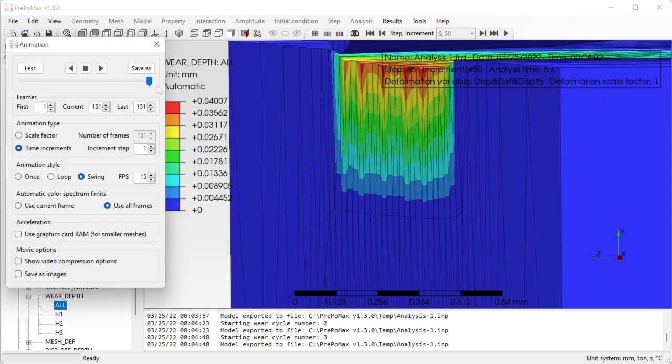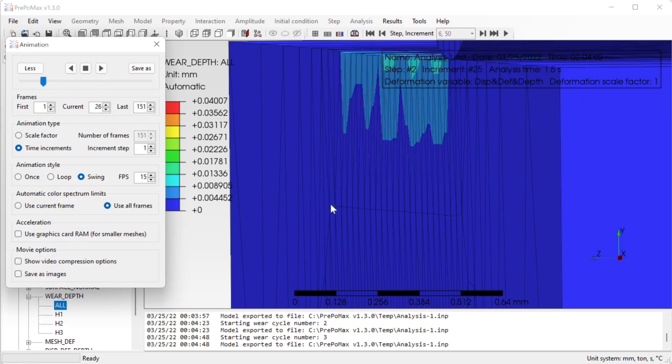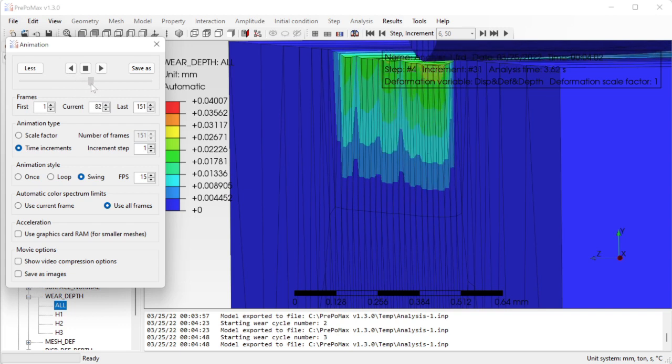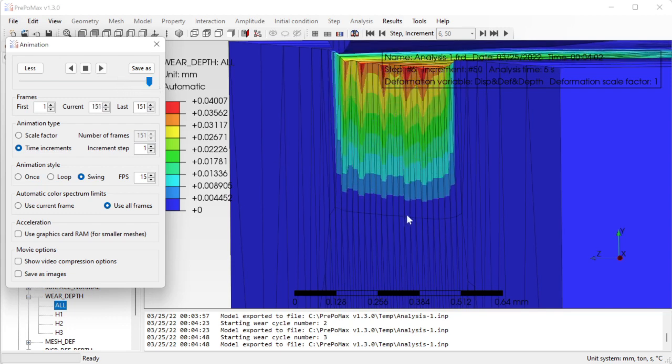around with animation, I can see that the nodes are first in a line, and then after one cycle, when the mesh deformation actually takes place, the nodes are pressed downwards. So the shape of the finite element is kept much better than when those nodes to the inside of the material are just not moved, so if they remain fixed.